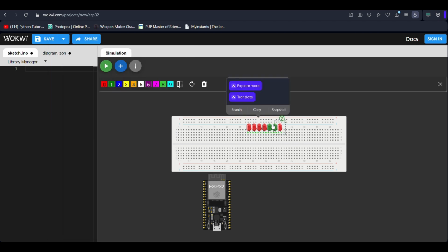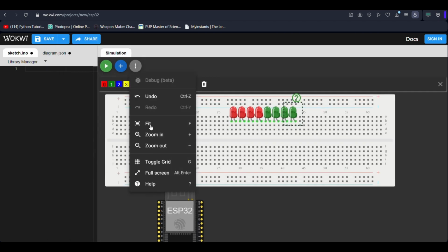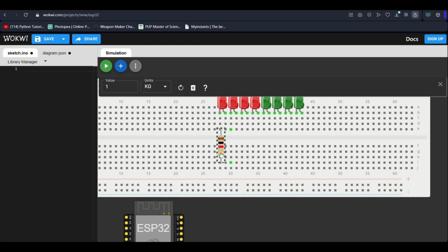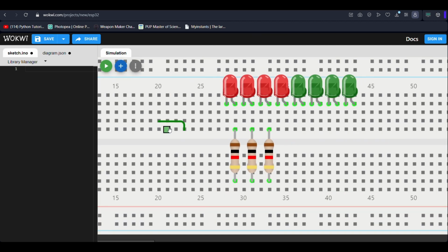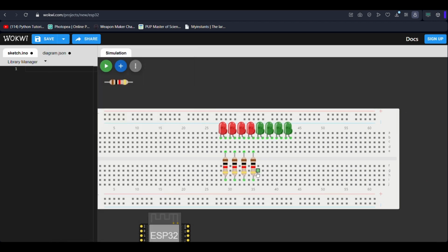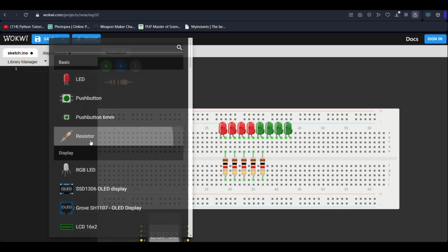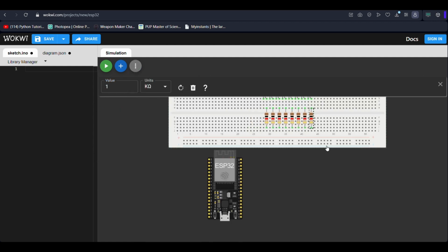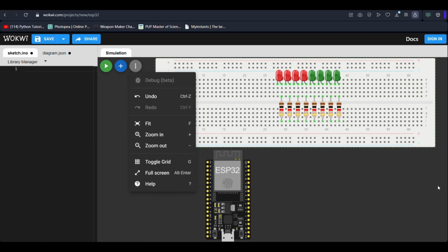In Laboratory Exercise 2, Program 2 focuses on creating a running light sequencer with a web server interface using an ESP32 microcontroller. To simulate and demonstrate the interfacing diagram, we utilize the Wokwi simulator platform. Firstly, we set up a breadboard configuration to accommodate 8 LEDs. Specifically, we used 4 red LEDs and 4 green LEDs, each paired with a 220 ohm resistor to control current flow and protect the LEDs. These components were meticulously arranged on the breadboard.